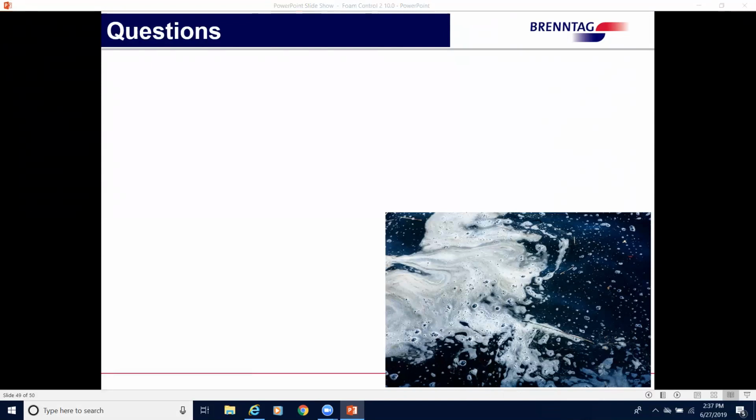Just to put it into an example, let's say you take a sample and you put in, I don't know, 100 mils of water and you put your air stone in and you run it for 5 minutes and then you start dosing product in. If you started with, let's say, 2 inches of foam on top of that, and you were to dose in however much defoamer, you can actually make a report and you can say, okay, I put in this much defoamer and the foam was knocked down X amount.